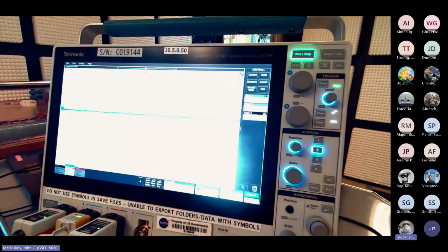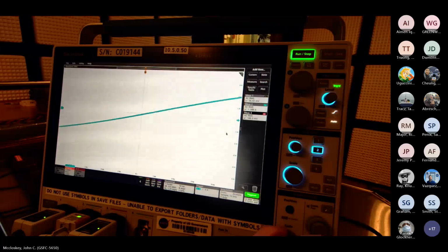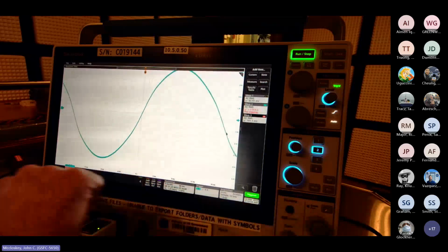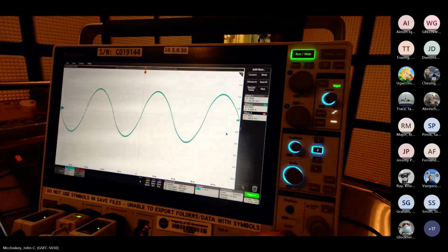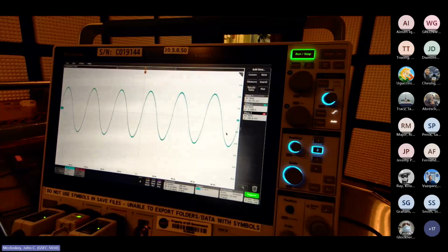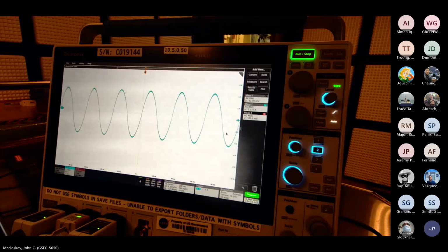We're going to have to adjust the time base. It's a pretty good amount of current, and we are clipping. All right, so we can ignore the top waveform, I'm sorry, the top measurement. We're only looking at measurement 2 here, ACRMS. So the 30 hertz playing back, oh, sorry, I hadn't adjusted the signal level.